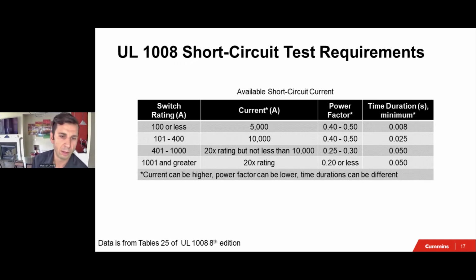And as a reference in here for you, again, the 0.05 seconds, the most common name that you use in the industry, 3 cycles, right? However, I want to remind you that in the UL 1008, there's no mention of cycles. It's mostly time. They just mention seconds.